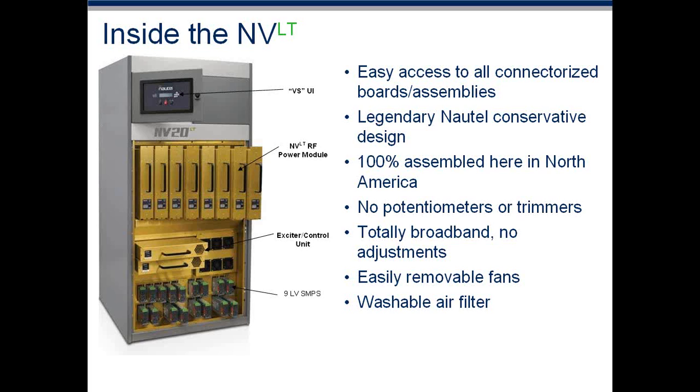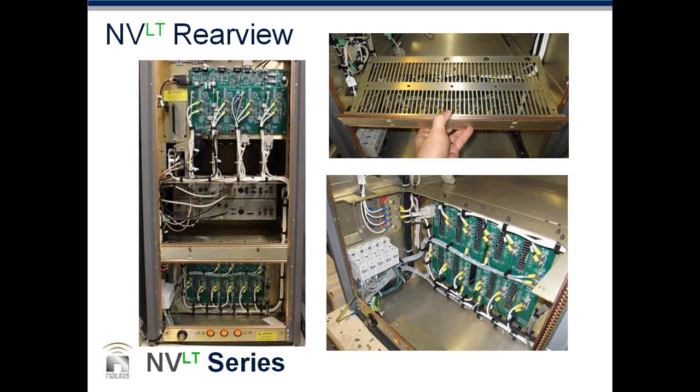In looking inside the NVLT, this is the 20 kilowatt, just like the one we have sitting down in the test room at the moment. There is full access to all the boards and assemblies. It's the Nautel design, and Nautel has a long history and reputation for reliability. It's all assembled here in North America. Again, no potentiometers or trimmers, not just in the exciter, but in the modules and in the controller cards and all of that. There's just nothing. It's all controlled via the AUI, which means you can do it from anywhere. Totally broadband, no adjustments, easily removable fans, and a washable air filter.